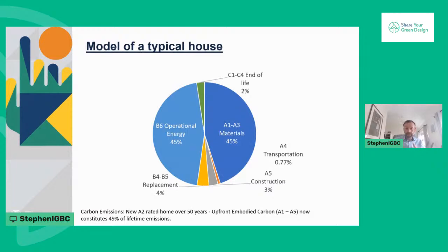I'm going to show you a few charts, but they're all based on this same data, just displaying it in different ways to show the profile of the emissions over time. So today, an electric heated home with a good energy rating, requiring about 50 kilowatt hours primary energy per square metre per year, in Ireland would come with a carbon cost of about 9 kilos of CO2 per square metre per year. And this factors in the electricity generation and transmission and all the fossil fuels still used in the grid.